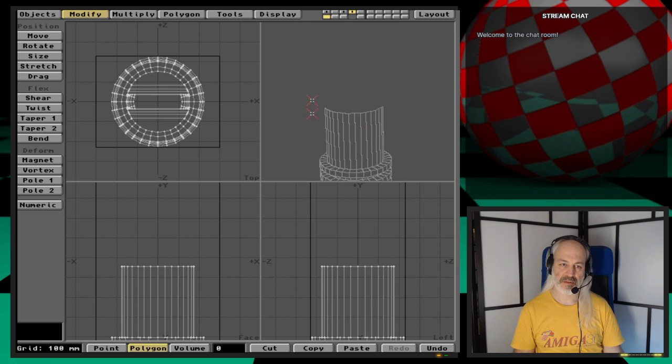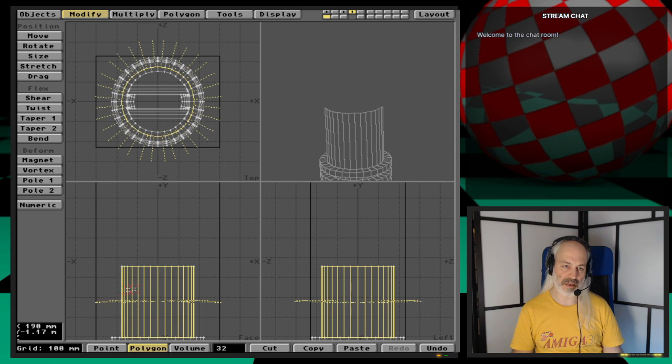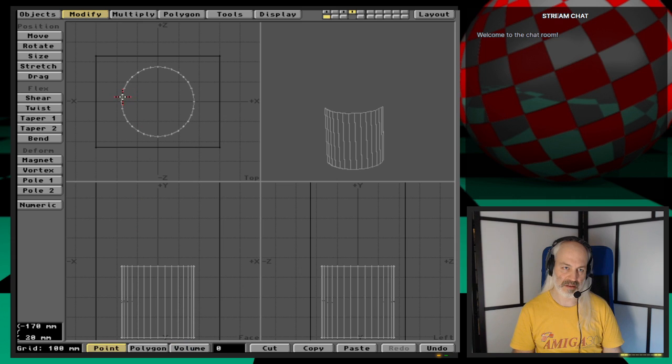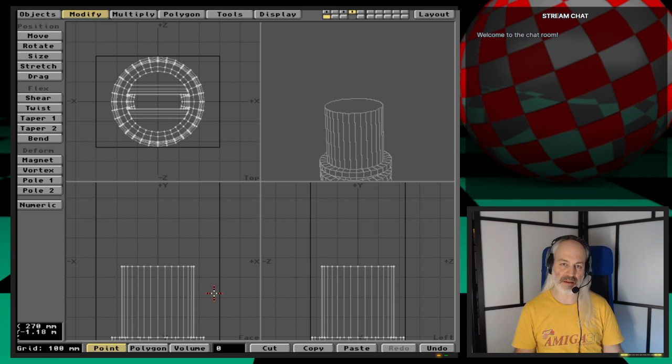I have a gap that I would like to fill, and I'll hide everything else except these selected polygons. Okay, taking this out, and I'll select all objects in this circle slowly, one by one, so they are in their order. Now when I'm done, I'm deselecting the lower part. I don't want anything to do with these, and press P. Yes, now I have my polygon, and I'm deselecting. I am unhiding everything else.